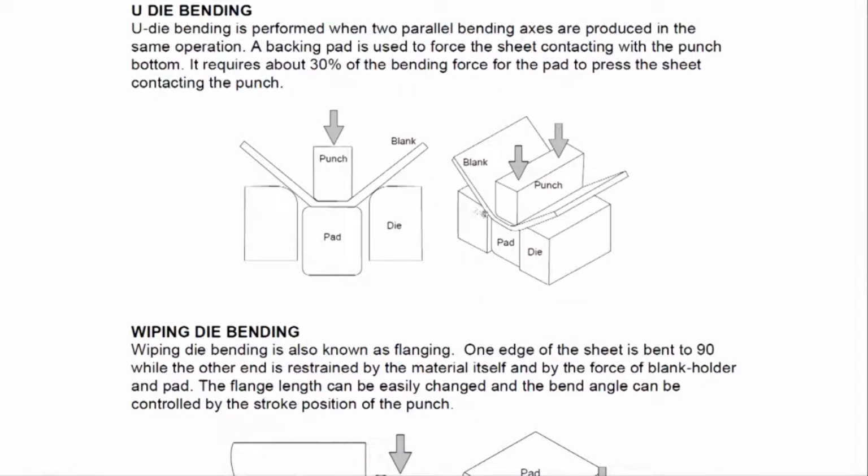So, in the blank there would have been a limb which is a little longer. And then just as you have a punch and a two-sided operation, we can have it on all four sides. So, you have a cup-like thing, the punch forces inside, and when it comes out you have a beautifully formed part.